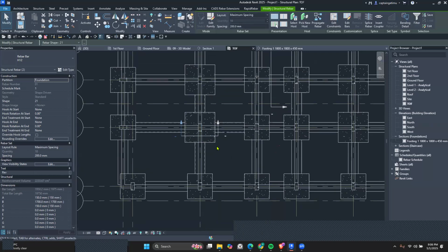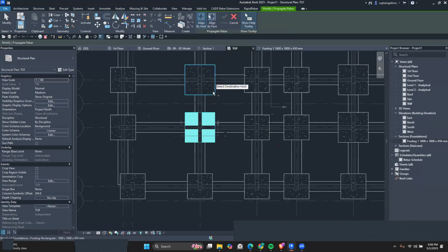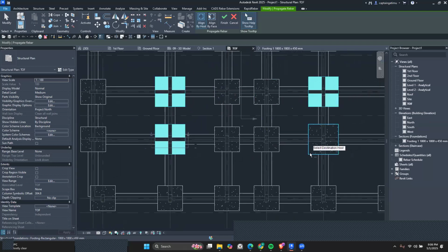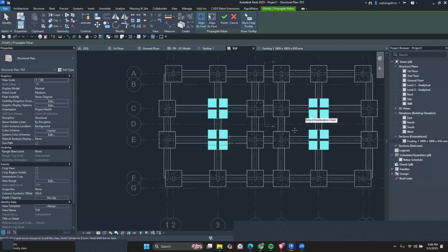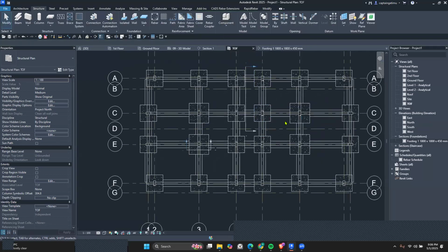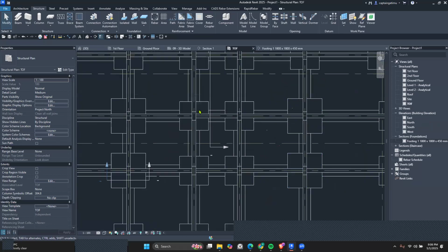And then after you select all rebar in hosts, you'll notice the contextual rebar ribbon changes. I want you to click on propagate, and then let's propagate by face. All right. Then let's propagate by host for this one. So select that host, select this footing and this one. And then after I've selected the footings that have the same cross section, click on finish, and then you're good to go. So you can see as I place my cursor over here, the rebars have been modeled in these foundations as well.